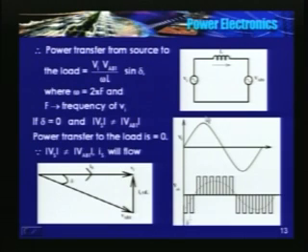So I will draw an equivalent circuit. This is the input voltage, inductor, and at this point we found that the voltage waveform is a stepped wave. Definitely it will have a fundamental component whose frequency is the same as the supply frequency, and a higher frequency component.